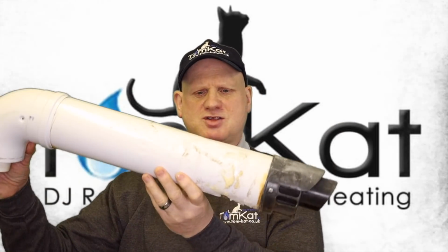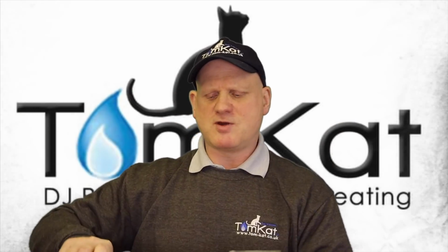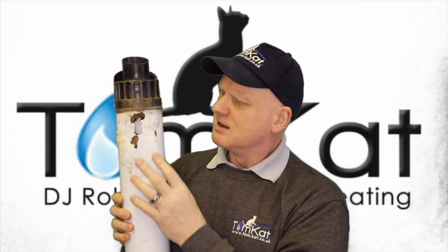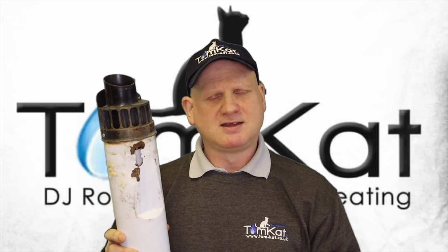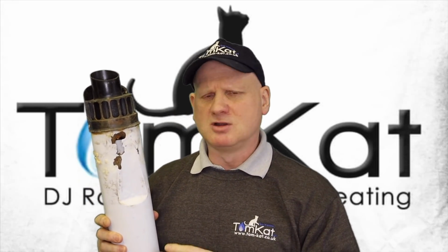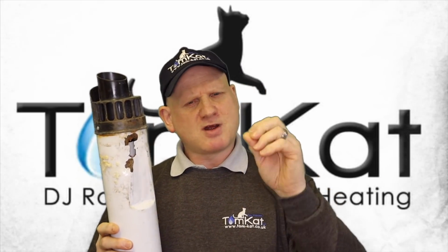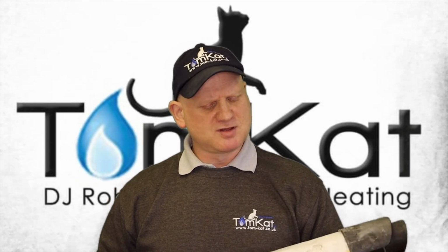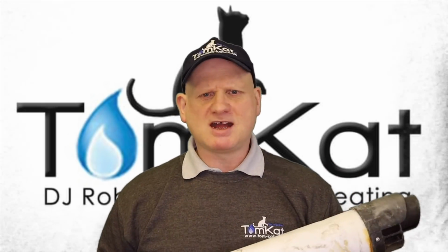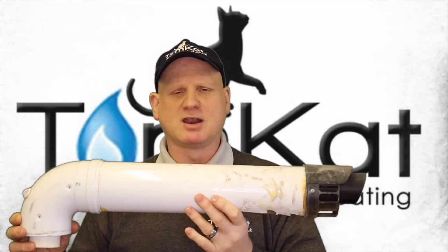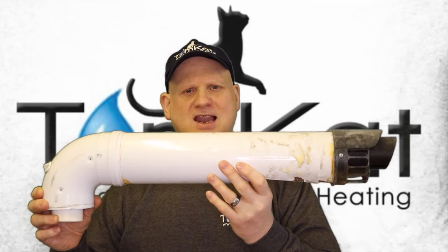Now, this flue was installed dipping down like that, so when the rain hit the flue, it ran down to the bottom end there, and that's how it ended up rotting away, because the flue was put on the wrong angle and it was sticking out the wall too far. So it's incredibly important when we're installing flues that one, we install them on the right angle, and two, we don't have them sticking out the wall. Now, what angle do we install the flues at? Well, if we're using the standard flue length of any boiler manufacturer, you would be installing it level.